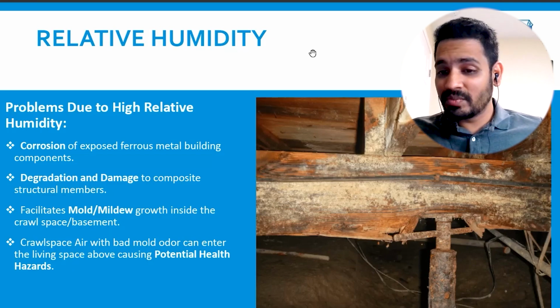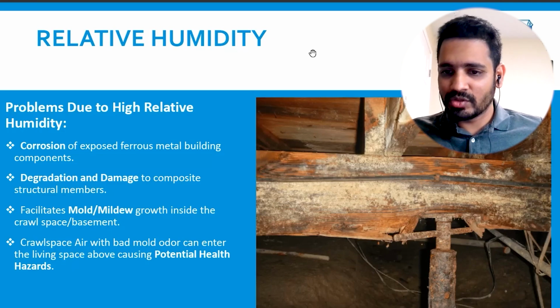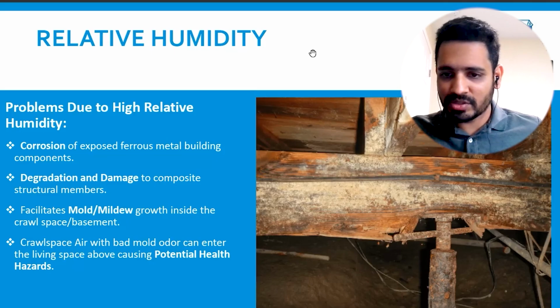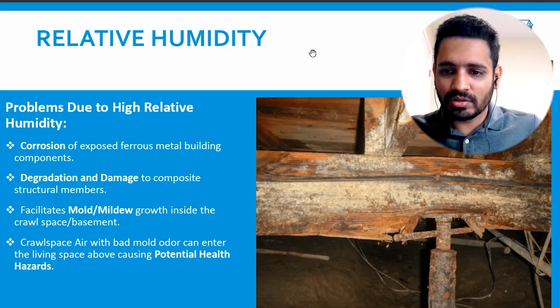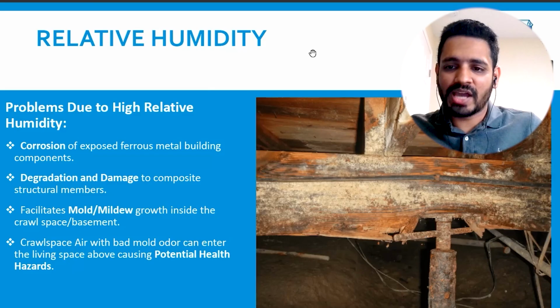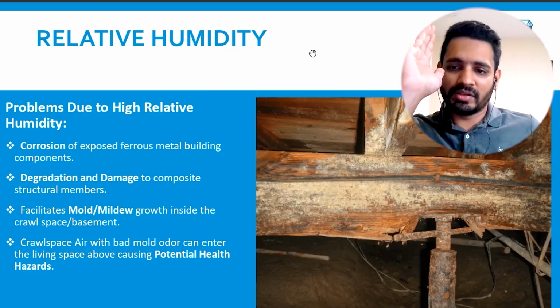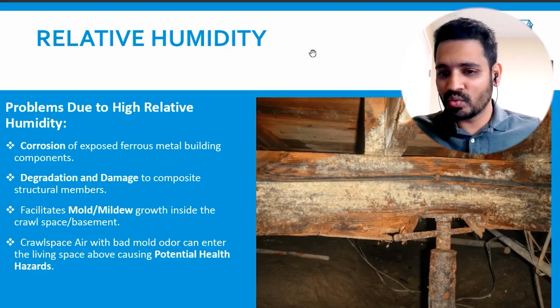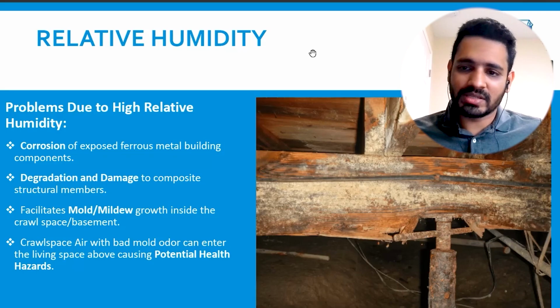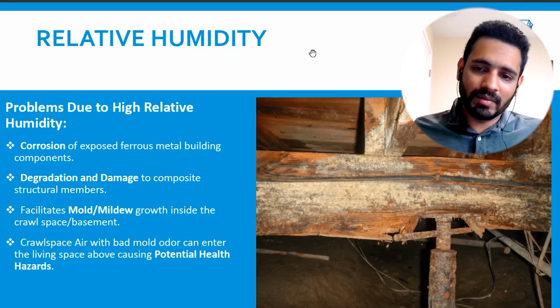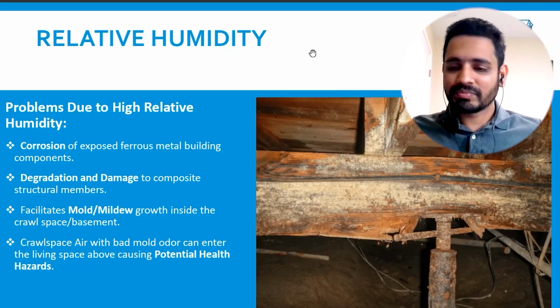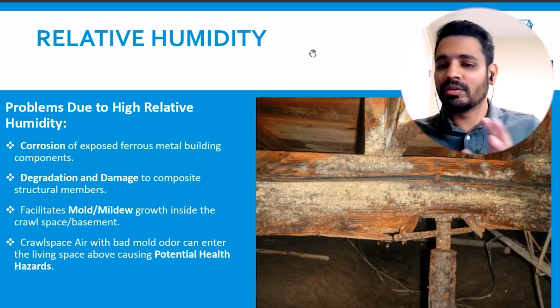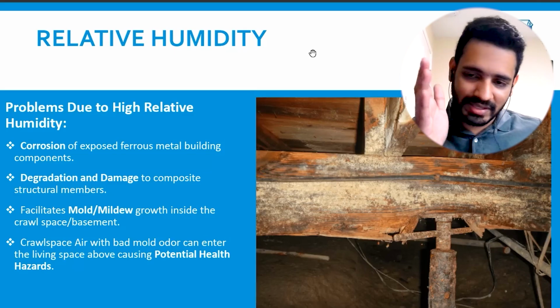And it wasn't because the screw jack was adjusted. It was because of so much moisture that the jacks corroded so much and started pushing up. And the moisture in the soil started pushing up the pier and the jack up, that it propped up everything. This is one condition in a crawl space in the Almaden region of San Jose. And there were multiple situations like these in this exact crawl space.